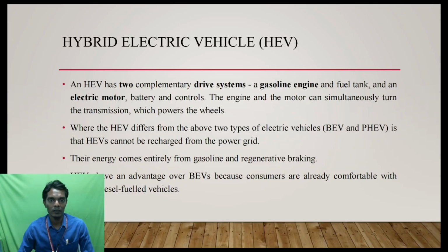So mainly the battery size, or the power stored in the battery, is not big compared to a battery-only electrical vehicle. Why? Because here the main source is only the gasoline engine, not the battery power. The gasoline engine is actually using the batteries to store the additional power.